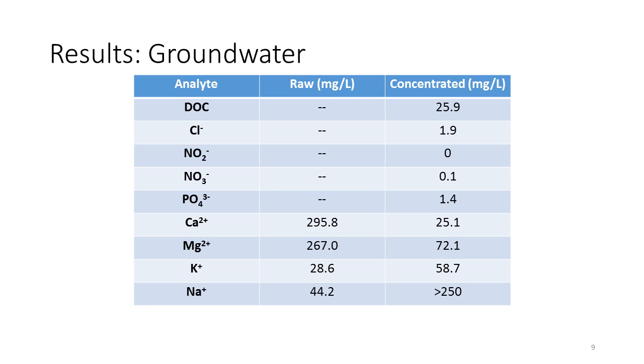I think because near the end of our ion exchange run, our ion exchange resin was getting fully loaded, indicated by a slight rise in the pH, and so I think that's why we have these high values for some of our cations. So we couldn't concentrate it as much as we would have liked, mainly because that osmotic pressure was getting pretty high, and we didn't want to take it to a dangerous pressure.